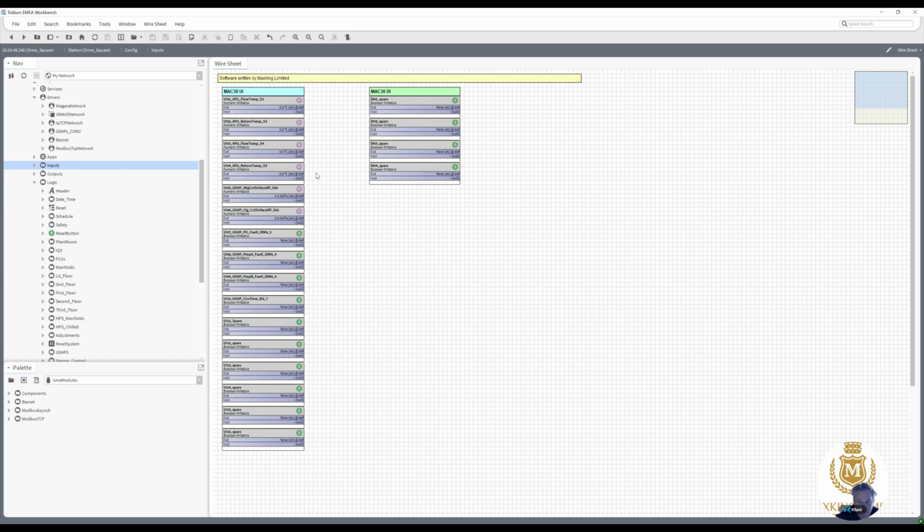So this is the inputs only, and we've got our 4 temperatures there, 2 for heat pump 1, 2 for heat pump 2, and then we've got our kPa differential on the heating circuit on the ground source side and the cooling circuit, which is what I need.